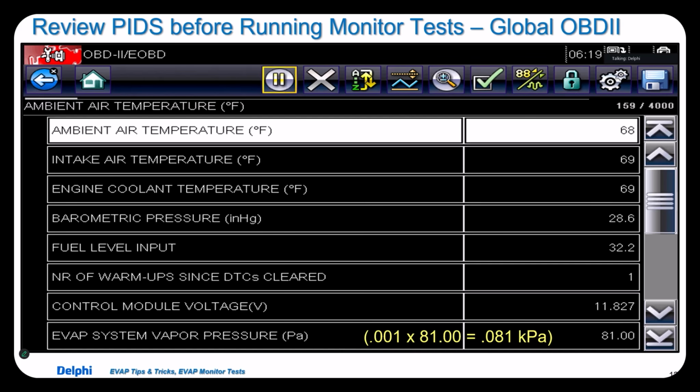And this car is cold, it's been sitting a while, and if you notice, all three are almost spot on, and you check your ambient temperature to this. If they're close to that, you know all three are in calibration. That's what the PCM is using to start its table lookup.